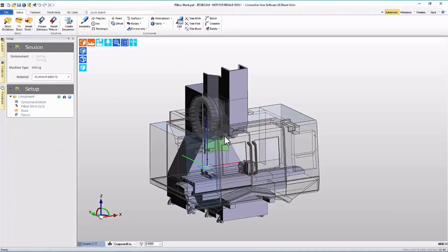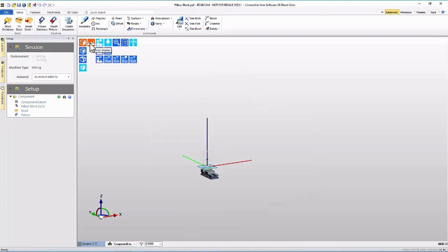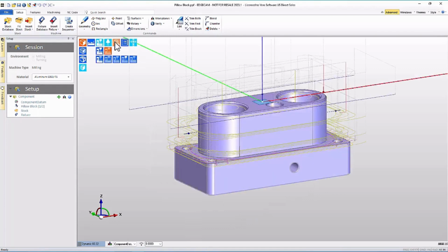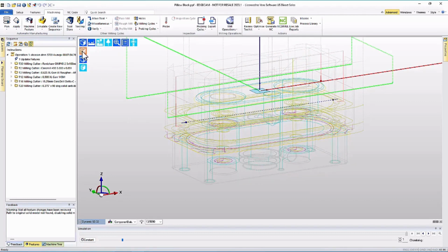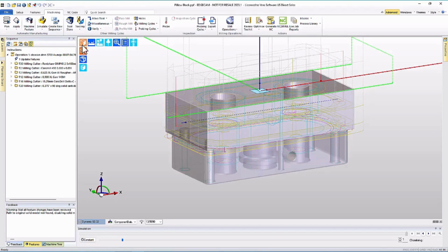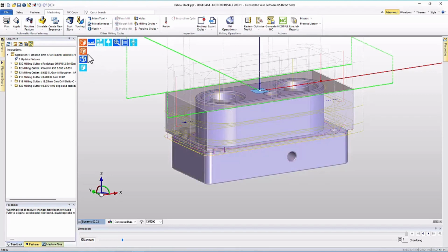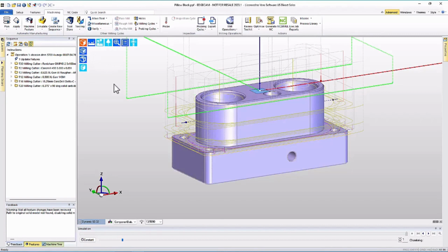So in the mill example, first of all, there's a lot of visibility that I might want to control. At one level, we see the CNC machine used in this machining sequence coming from the post-processor. As many of you likely know, you can easily turn off the display of the machine, the fixtures, zoom extents, and see the part. But the part still has a mixture of part, stock, tool path, and all that. With the solid rendered, we see the solid. We can unrender it to see better detail sometimes. We could render the stock, or both could be done together, really up to the user.